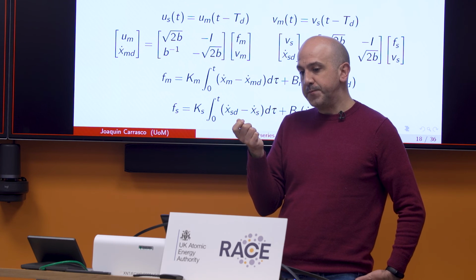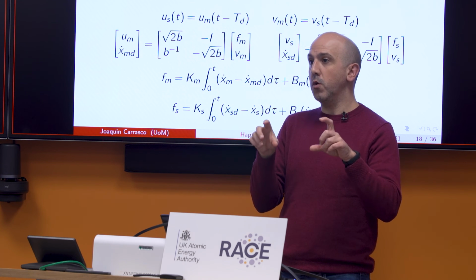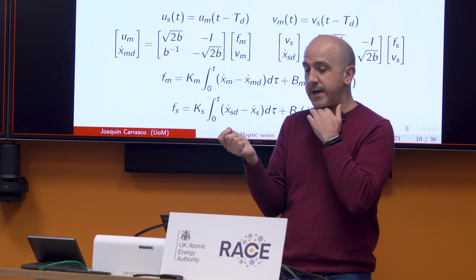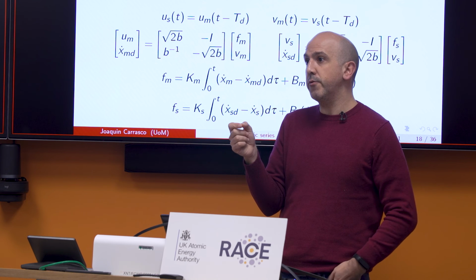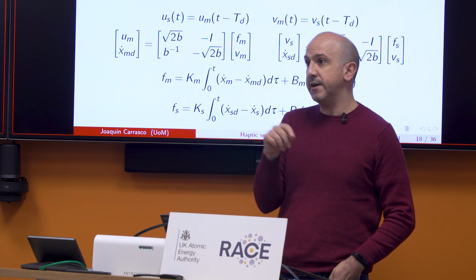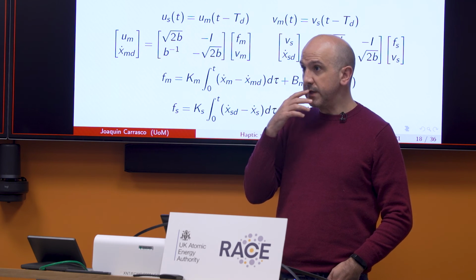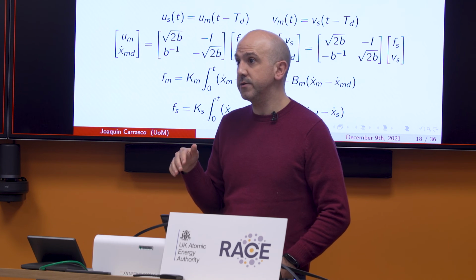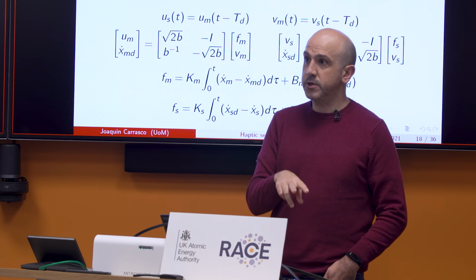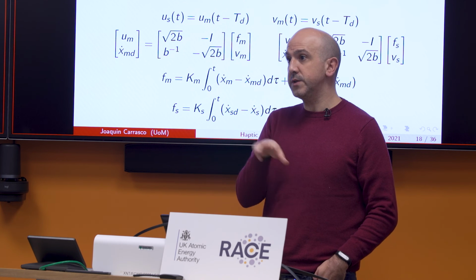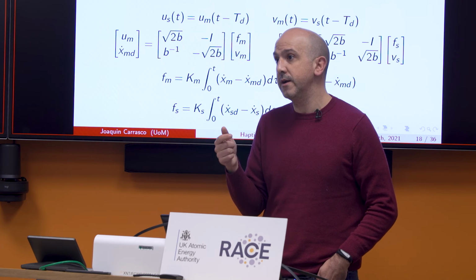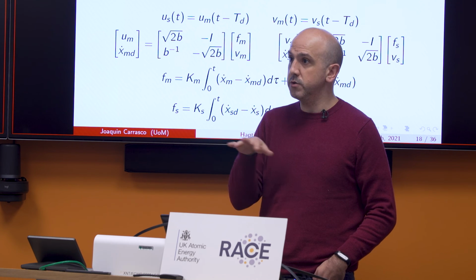Anyway, this is called position feedback configuration. In other configurations, you can actually send the force of the environment, and they are called position force architectures. So you have 2 channels, position. You have 3 channels when you are able to measure the force of the environment, and you have 4 channels if you are able to measure everything.